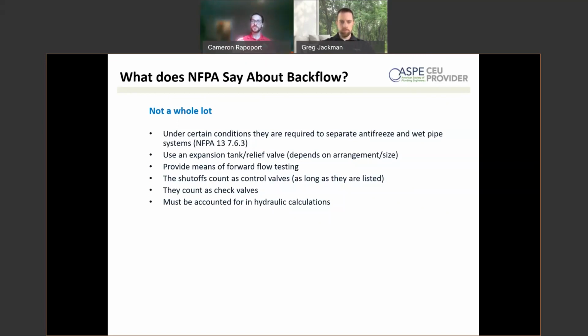Right? Retroactive installations require revised hydraulic calculations. If you're removing a backflow preventer and you're installing a backflow preventer that is not the exact same make and model, you really have to revise those hydraulic calculations. You could go from being okay to being in trouble with a higher pressure loss, especially if you're switching backflow preventer types.